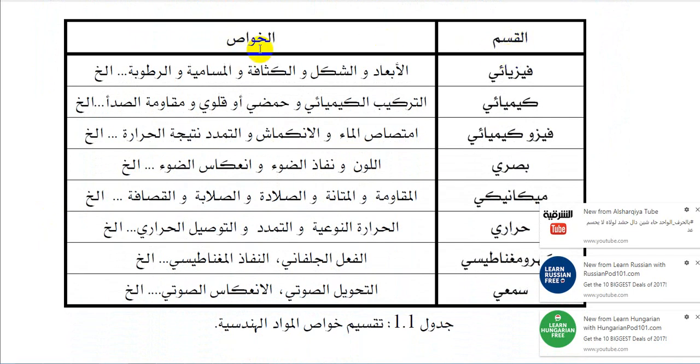The features, the sections and properties: physical, dimension and shape and density and porosity and humidity, etc. Chemical, the chemical compositions, alkali or acidic or corrosion resistive, etc. Physiochemical, water absorption, shrinkage and expansion due to heat, or thermal expansion, etc.